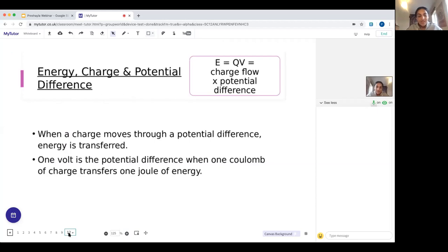What the earth wire is there to do is, if there happens to be a fault with the plug or a surge in current, to prevent us getting an electric shock, it takes the surge in current and pushes it into the ground. What I mean by ground is it could be an electrical wiring underground, or a water pipe underground, or something like that, and it takes the current and discharges it away, so that it doesn't harm us and doesn't give us an electric shock. It's a low resistance path, so that it can allow as much current as possible to come through it.